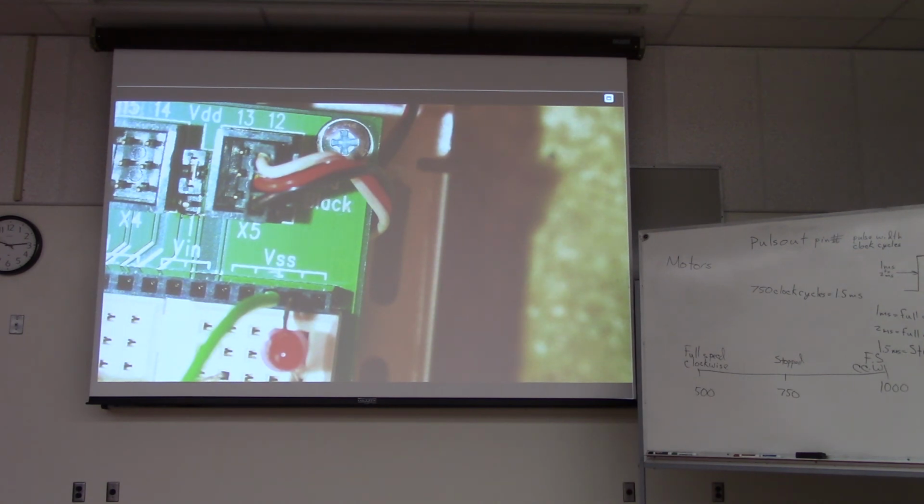If you have two circuits and they're going to work together, you almost always want to tie those two grounds together so that they are at the same potential. Otherwise, it can start doing weird things. There are problems called ground loops when the ground is not the same. So it is not a universal thing.